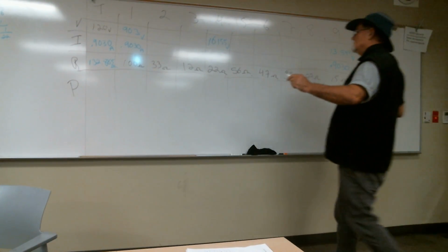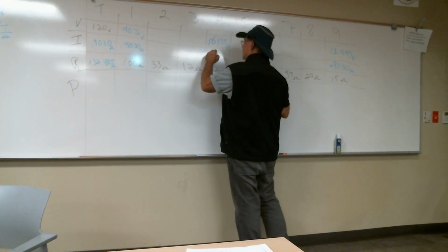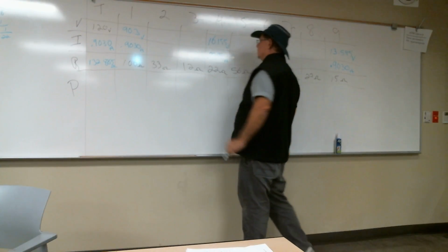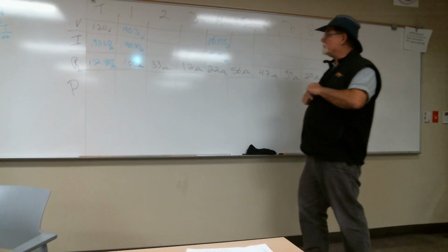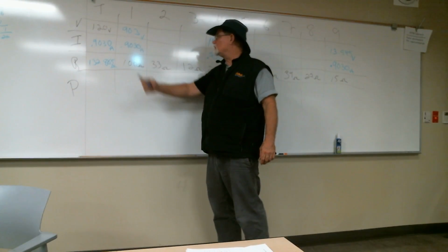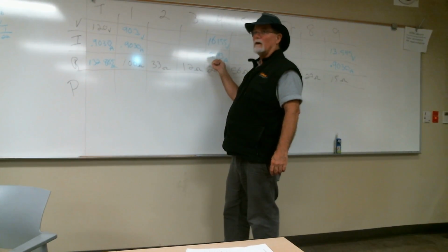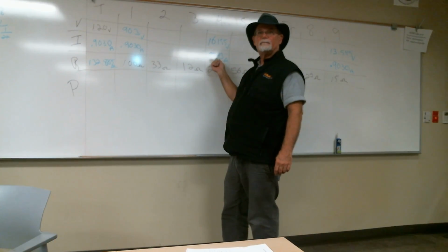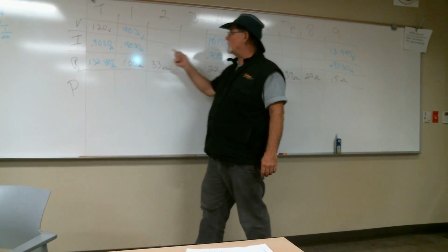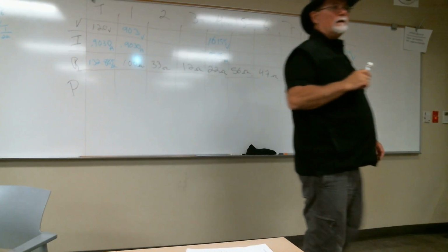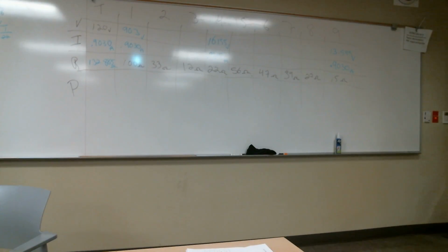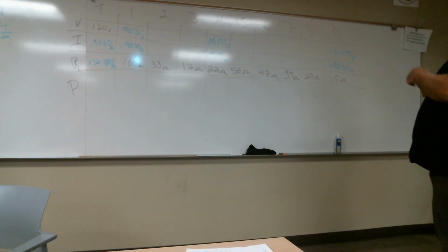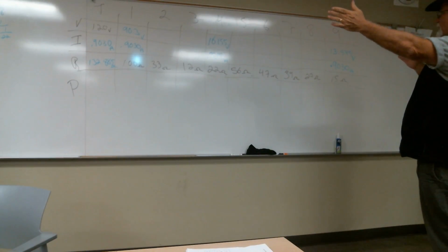Okay, so 16.155 divided by 22 is 0.7343. That seems about right. 0.7343 amps. So some percentage of this amperage is going by number 4. The rest of it's going through 2 and 8. So if I subtract this from here, that's what must be going through 2 and 8. Right? So it's going to be 0.1687. And I'm going to plug that in number 2 and number 8.